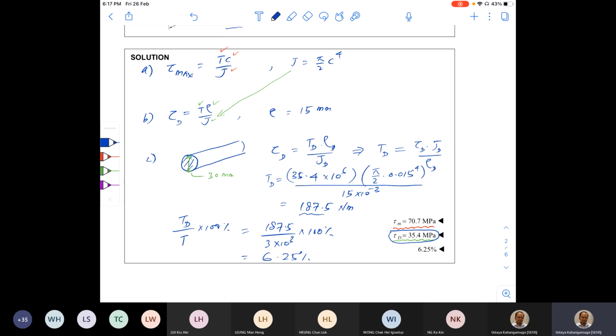So if you have, let's say, an office chair, the office chair's vertical shaft is hollow circular, right? Because when we turn around, it is subjected to a torque. So the best shape to support a torque is a cylindrical shape, but a hollow circular shape is much better because there's no point in having that middle material which will not support that much torque, right?